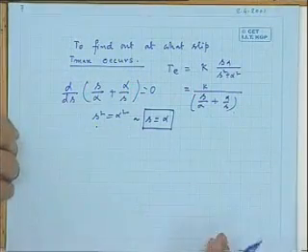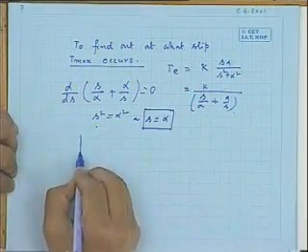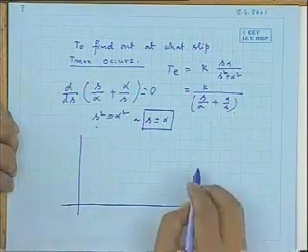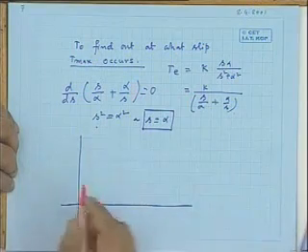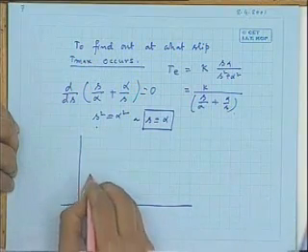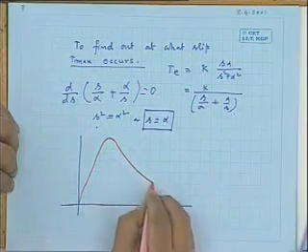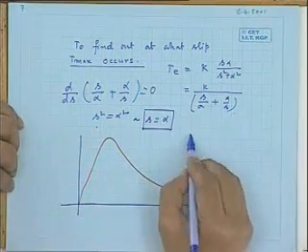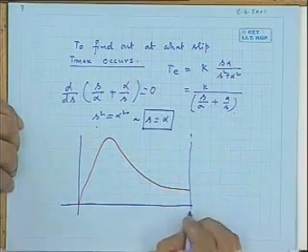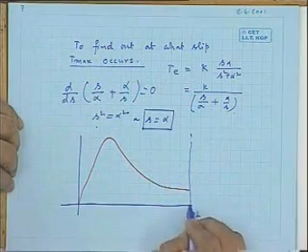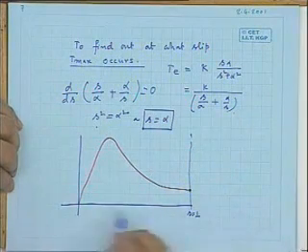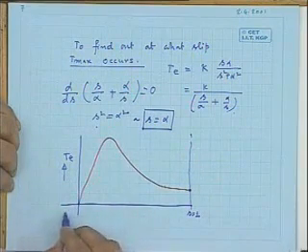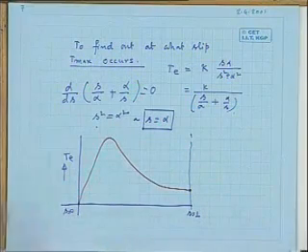Now the important thing I will try to tell is that with this torque slip characteristic we can explain many things. For example, you draw a torque slip characteristic now like this, and don't correctly put the value of slip. So this is s equal to 1. This point represents the standstill condition. This is Te and this is s equal to 0.